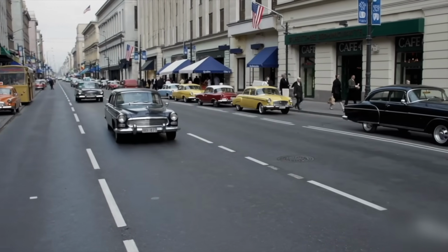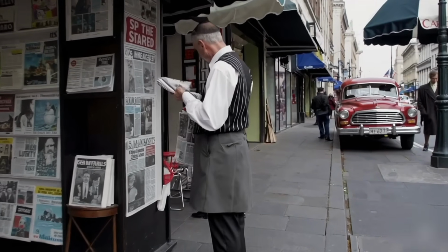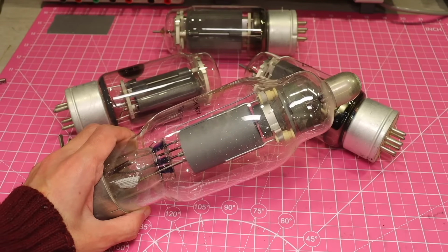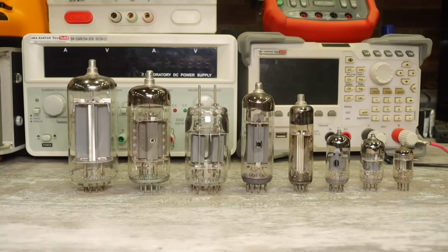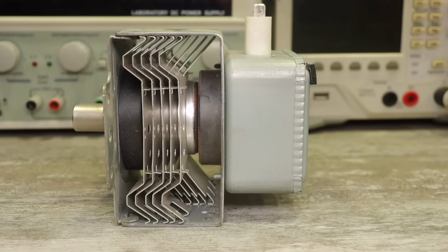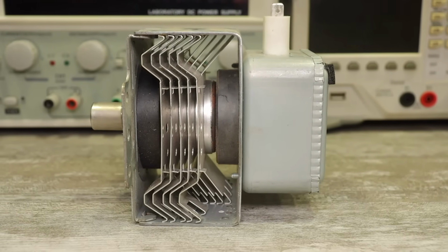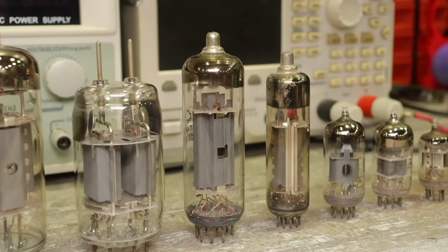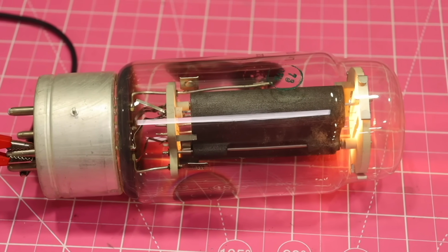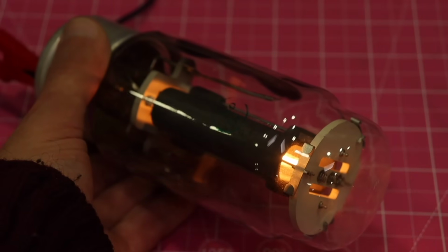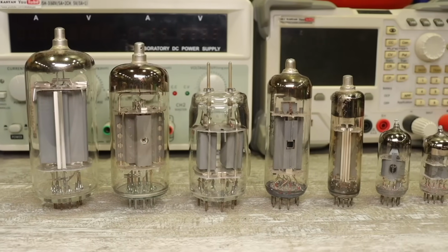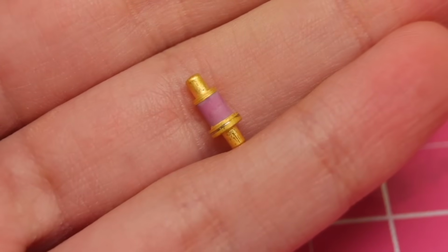The 1960s were remembered for many events. In terms of technological development, especially in the electronics industry, the world was just beginning to move away from bulky and power-hungry vacuum tubes in favor of compact semiconductor devices. Of course, there were fairly high-frequency vacuum tubes capable of operating at tens of gigahertz. They were used for amplification, radar, and even satellite communications. But vacuum tubes heat up, have a short lifespan, require high filament currents, and need high anode voltages. And some vacuum tubes are even sensitive to how they're installed. Scientists have always been searching for solutions, something better, and the Gunn diode became one of them.